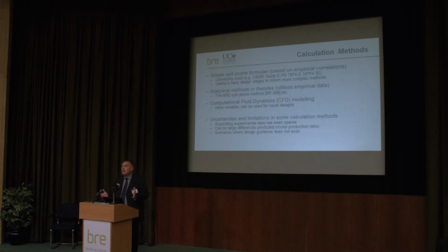Now, there are various calculation methods available to the fire engineer for calculating entrainment into plumes. There are generic types. The first of these is the simplified spill plume formulae. I love these. These are really good.